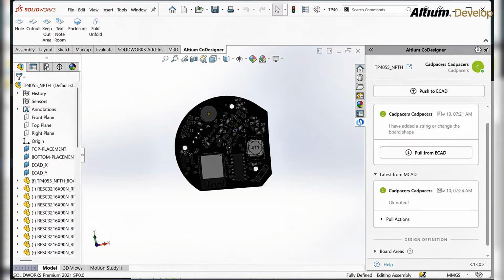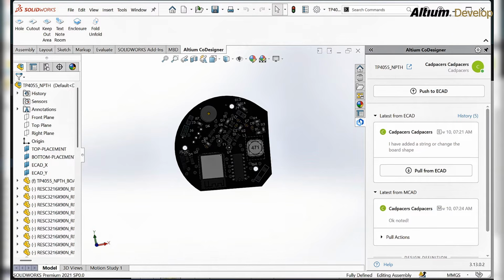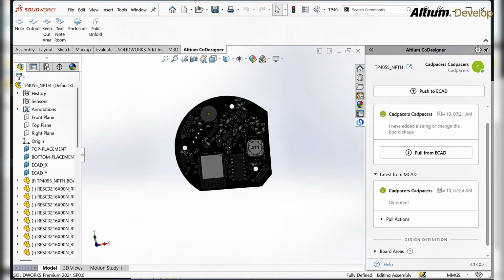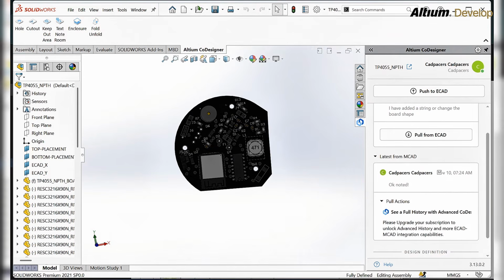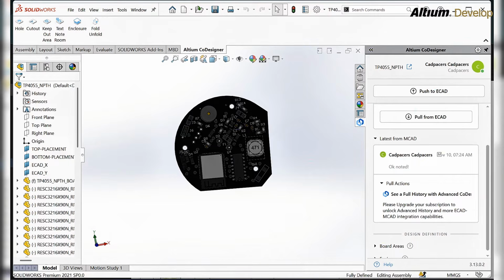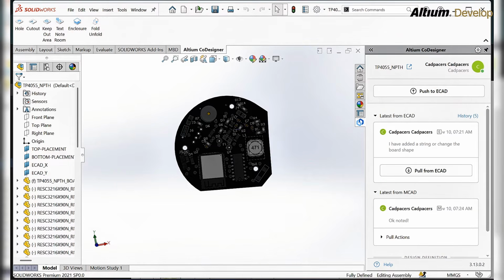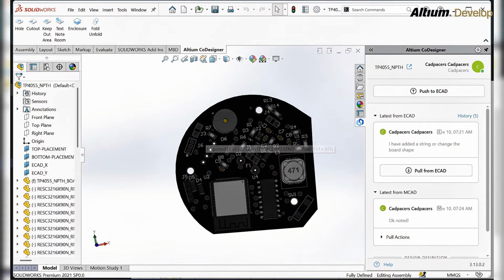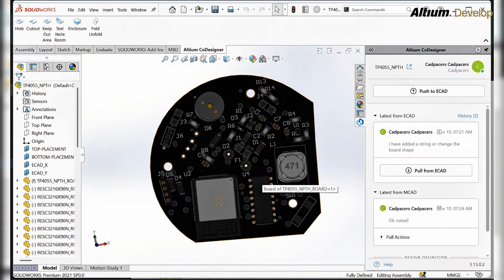Now we will see how the manufacturing release works in the Altium Designer workspace. It's the same procedure as we usually release the board for manufacturing, by right-clicking on the project in Altium Designer and going to the project releaser option to release the project or the manufacturing files. But there are a few small changes, so we will discuss those changes. First, do a project release, same as we do in our conventional Altium Designer software. So do the project release and you will see this interface.